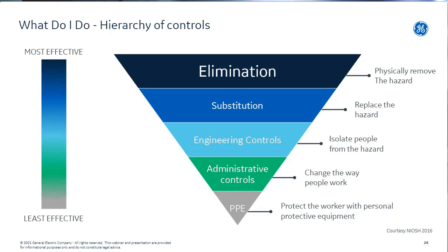So what you do, from the occupational health and safety point of view, is we have our hierarchy of controls, where we always start with trying to get rid of the hazard itself. As an example, if I have combustible material and I can switch to another grain size, then I take the combustibility away, and that is elimination. Substitution means that we try to replace one hazard with something which is a little less hazardous, but already a little bit different.